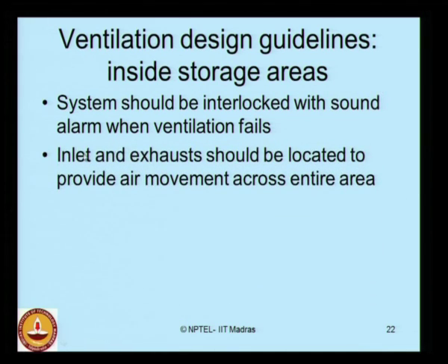The inlet and exhaust should be located to provide smooth air movement across the entire floor area. This is very important. In layman's language, people call this good cross ventilation. So, your inlet and exhaust should be located on the floor in such a way that the air movement is smooth and the air moves practically across the entire area of your floor.